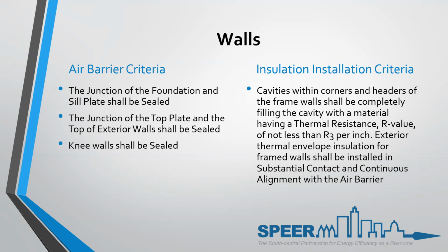And the previous presentation that we did was talking about advanced framing, and it's not really going over the top advanced framing. It's making sure these little things like meeting the code intent to insulate corners and headers are done. I didn't go into detail with that because we've talked about it before, but putting an R3 board sandwiched in headers is a way to insulate the headers, and then making sure that you do 2-stud or 3-stud corners to